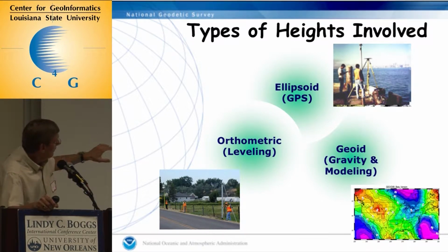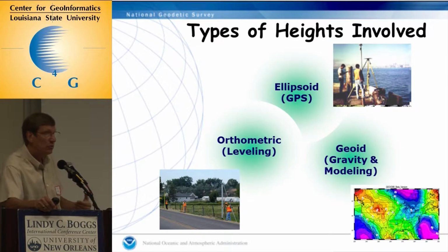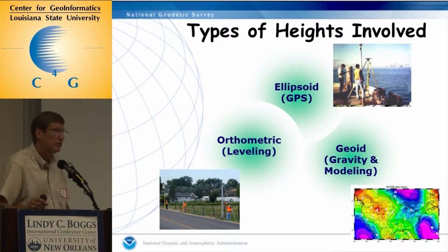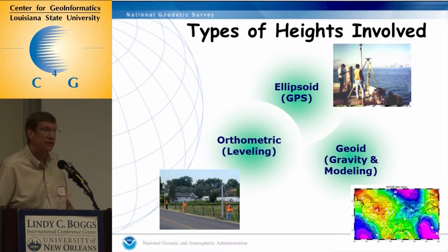So we'd like to spend some time, and in this workshop, you're going to hear more about the geoid model, which is probably one of the most critical parts now of doing the GPS-derived orthometric height. In the beginning, you worried about, well, how can I get an accurate ellipsoid height? Well, the procedures really stand out. Getting more satellites up there helped. Better processing tools, better instrumentation. That all really helped and minimized the errors.